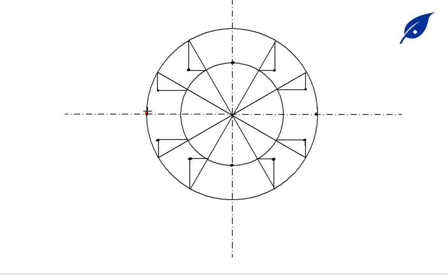Using French curve or flexible cable, flexible roller, to connect all these points to each other to give us a perfect ellipse. Now, when you're using any of these, you can't connect all of them at once.